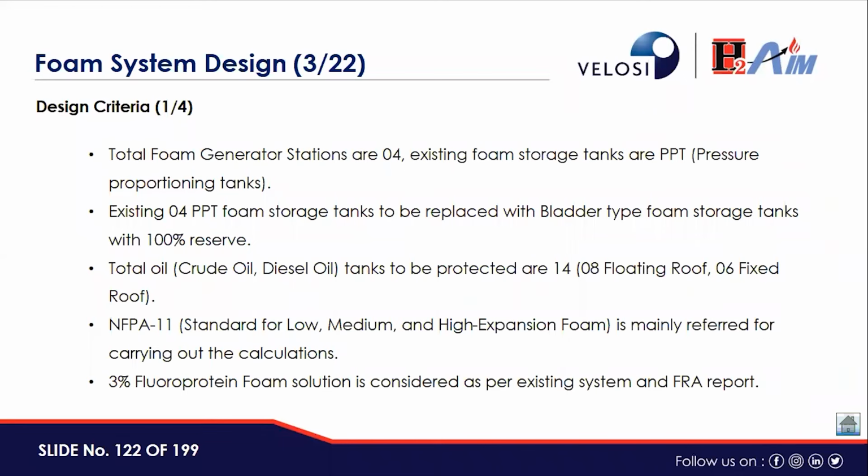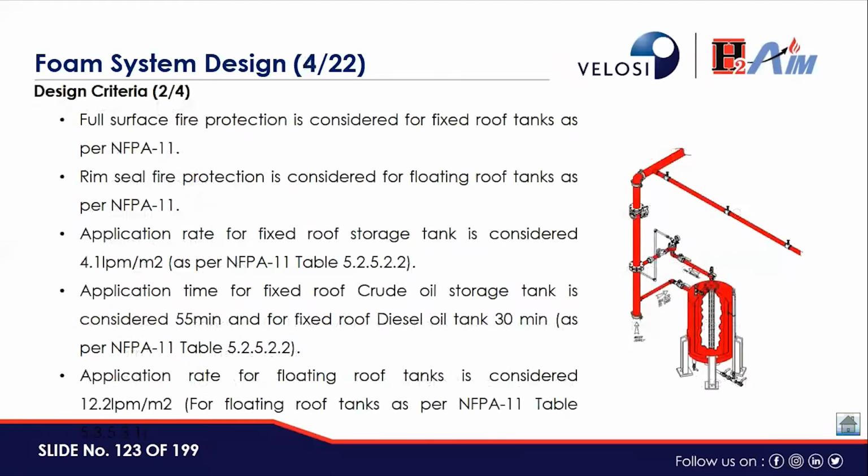Total oil tanks to be protected are 14. Out of 14, 8 were floating roofs, 6 were fixed roofs. And then NFPA 11 is mainly referred to for carrying out the calculations for the foam system design. 3% fluoroprotein foam solution is considered as per the existing system and FRA report. Full surface fire protection is considered for fixed roof tanks as per NFPA 11. Rim seal fire protection is considered for floating roof tanks as per NFPA 11.